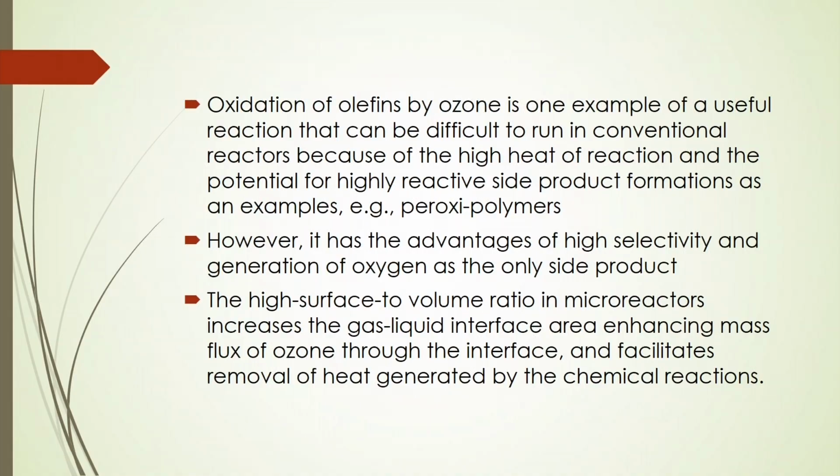However, it has the advantages of high selectivity and generation of oxygen as the only side product. So, the high surface to volume ratio in microreactors gives an increment of the gas liquid interfacial area that may enhance the mass flux of the ozone through the interface, and it facilitates the removal of the heat generated by the chemical reactions.